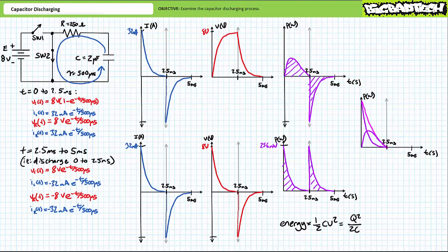During the discharge process, things flip-flop. During the discharge phase, the resistor experiences time-variant negative voltage, negative current, and thus still dissipates time-variant positive power. During the discharge phase, the capacitor also experiences time-variant positive voltage. However, current must necessarily be considered negative, and thus dissipates time-varying negative power. Thus, dissipate might not be the best choice of words. A better choice of terminology might be supply or return.